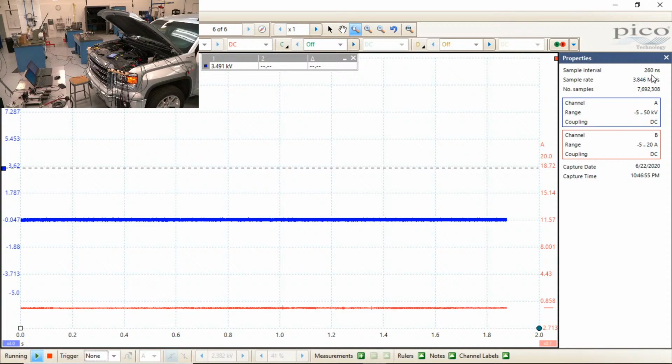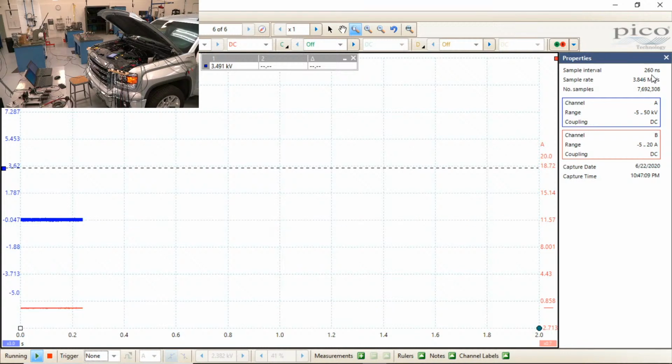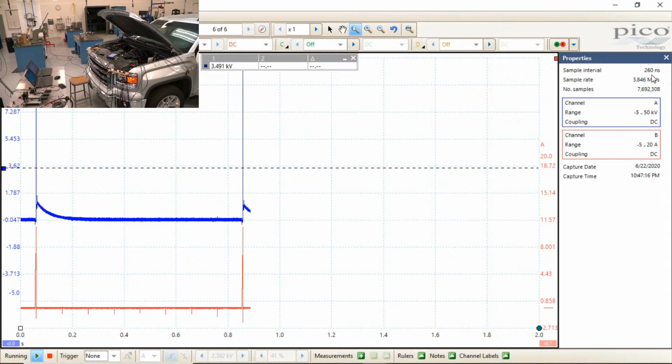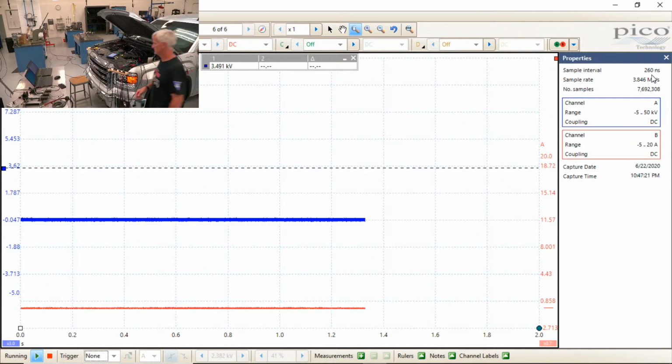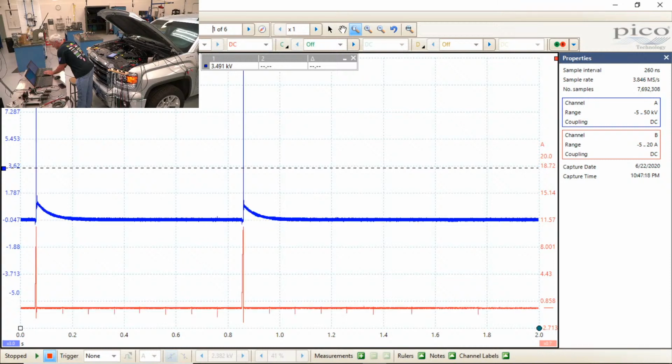So I'm key on, engine off. I go wide open throttle. I got a couple kicks there, but the problem that I had is for some reason it was killing the ignition. Let me try it again. A lot of times it will just kill fuel, but it looked like it was trying to kill ignition on me there too. But all right, if I stop it, did I stop it in time? I only had 6 screens recording there. Oh, good, I got one.